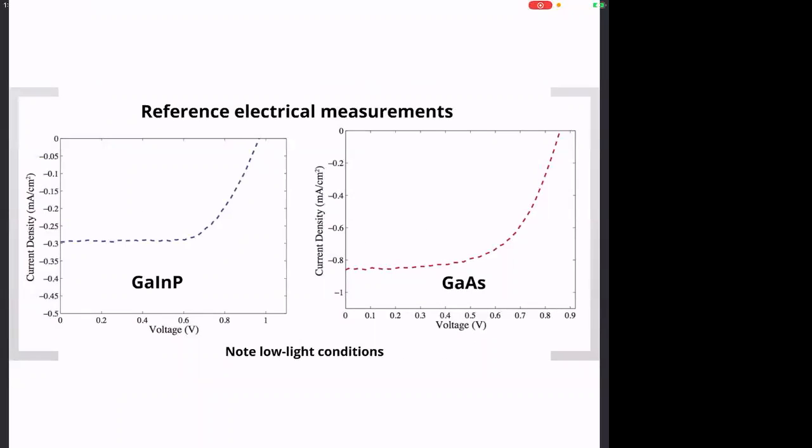First we measure the current-voltage characteristics. And of course, the current is negative, as you recall from circuits. A solar cell is a photodiode, which is reverse biased. So when light hits it, you generate electron hole pairs, which can then flow in the opposite direction of the applied voltage. So that's why this current becomes negative, right? And then you have the voltage, and you get a curve which looks like this.